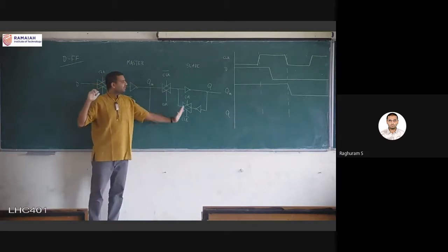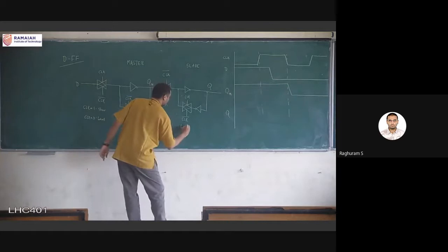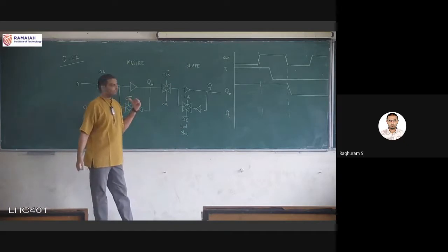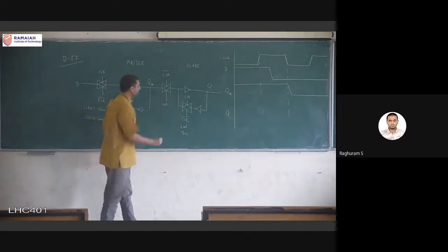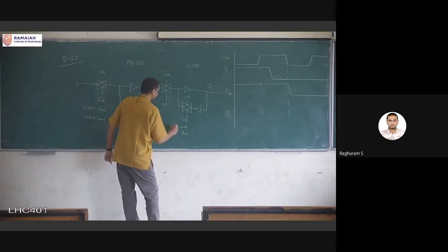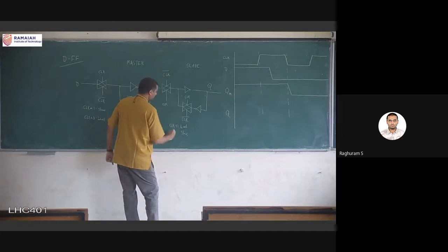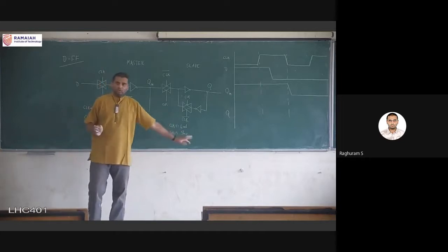Now I just consider this as a new latch which is load and store. Here it should be opposite of the previous one. We can check that also. When clock equal to 1 it will be loading, and when clock equal to 0 it will just be storing the old data.